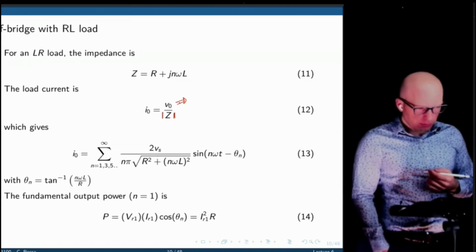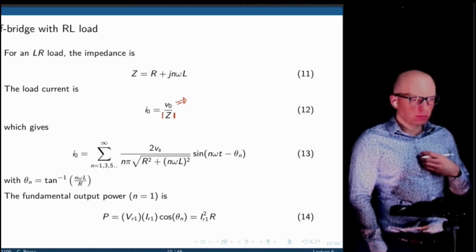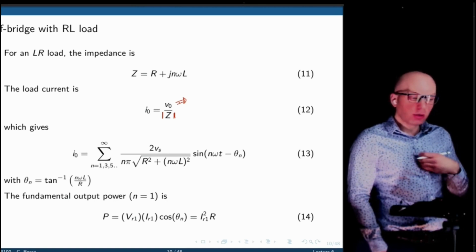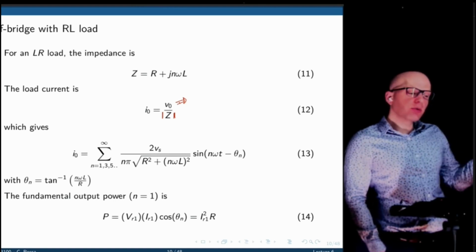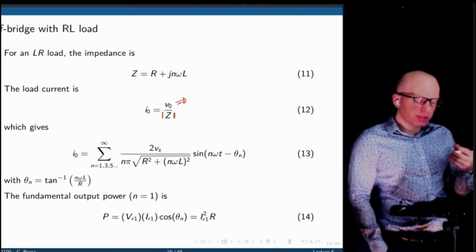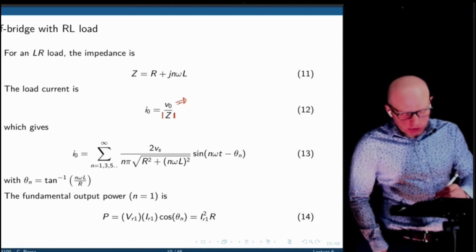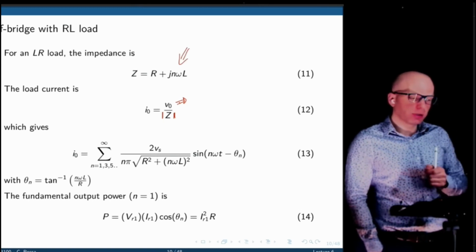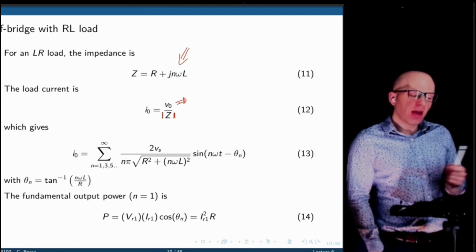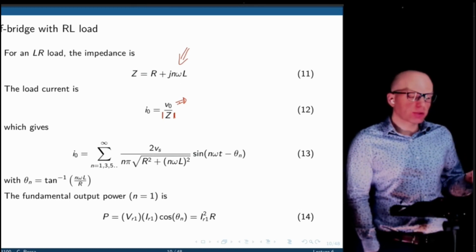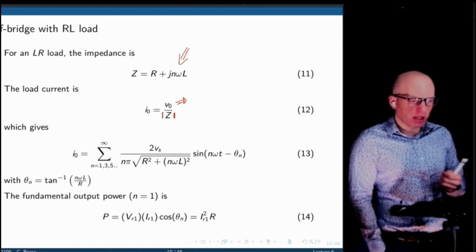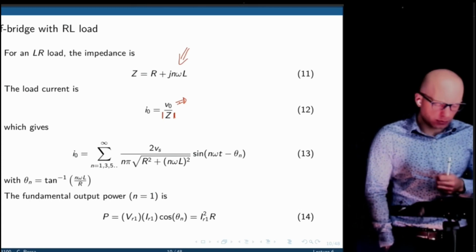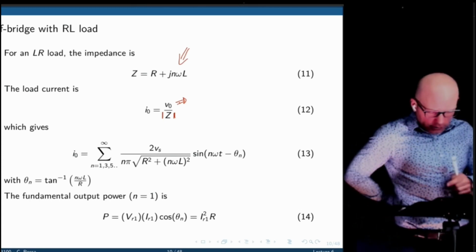So that means like the same way we neglected the higher harmonics in terms of useful power, we can't neglect the impedance when n is large. Later we'll make that assumption, but just to be consistent, we need to acknowledge that now the impedance depends on which harmonic we are attempting to model. Right? If you're only concerned with the first one, then n equals 1, and impedance is not dependent on n anymore. And that's what I'm going to do next.